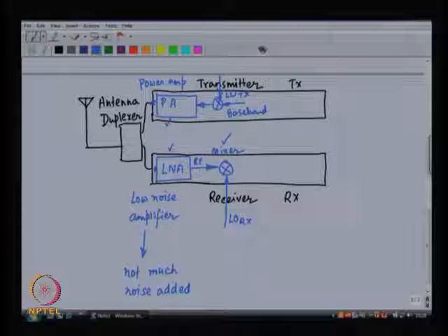So, as I was saying, the transmit side local oscillator will be oscillating at a frequency different from the receive side local oscillator. Why? Why does it have to be the case? Why can't I transmit and receive at the same frequency? Because if I don't have them different, then mostly what I am going to be hearing on the receive is an echo of what I transmitted.